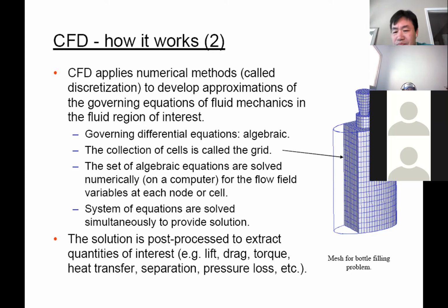After the run, what Fluent does is calculate values, for example velocity, pressure, and temperature, on every grid point. You see the grid intersection? This is called a grid point. It won't calculate anything in between grid points. You see the cells, these grid cells, but what the computer actually does is only calculate on the corners of each grid cell. Does that make sense?